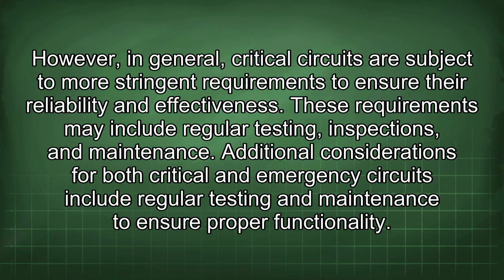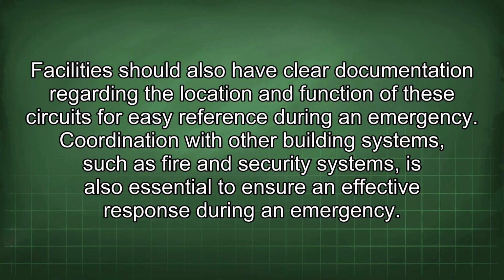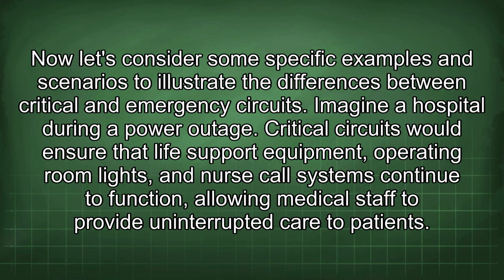Additional considerations for both critical and emergency circuits include regular testing and maintenance to ensure proper functionality. Facilities should also have clear documentation regarding the location and function of these circuits for easy reference during an emergency. Coordination with other building systems, such as fire and security systems, is also essential to ensure an effective response during an emergency. Now let's consider some specific examples and scenarios to illustrate the differences between critical and emergency circuits.